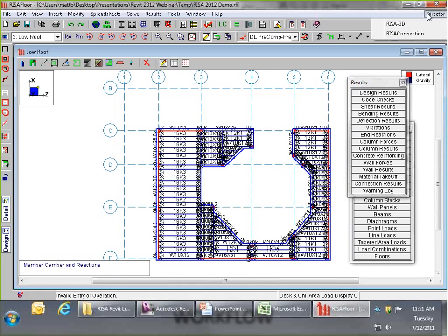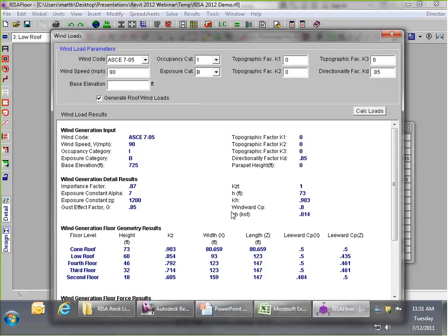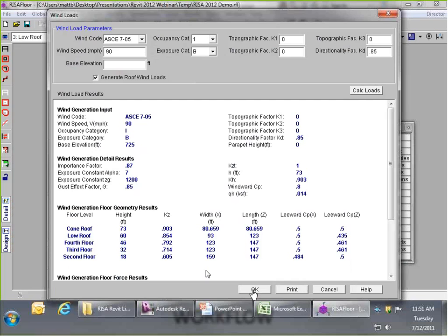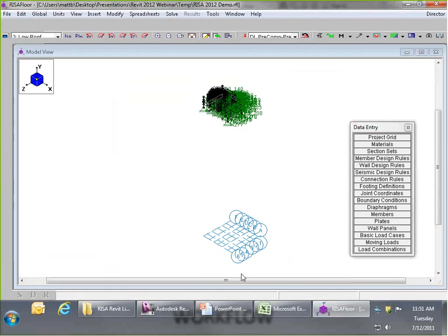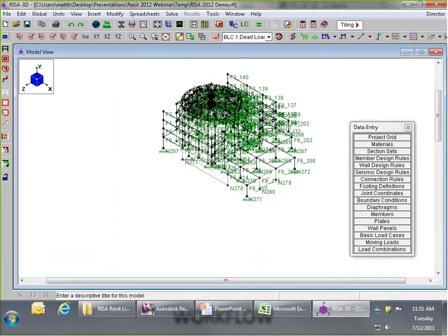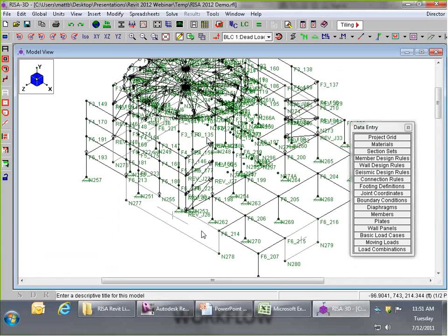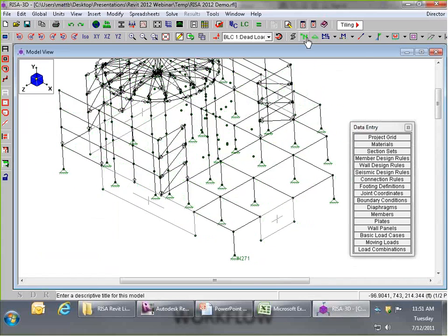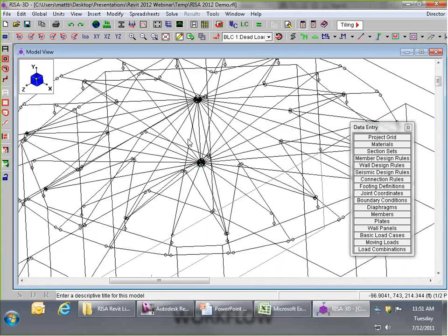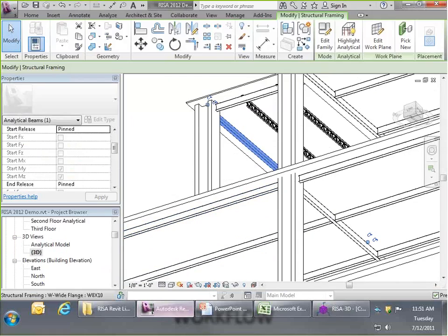I'm going to use my director tool and go into RISA 3D now. And here it's going to ask us for information about the wind loads and seismic loads. And so what we find here is everything that is relevant to the RISA 3D model. Now, one important thing, here my whole dome is set up, and we can see all those H-brace members have now come in, so we can get a full finite element analysis on this one with correct stiffness.